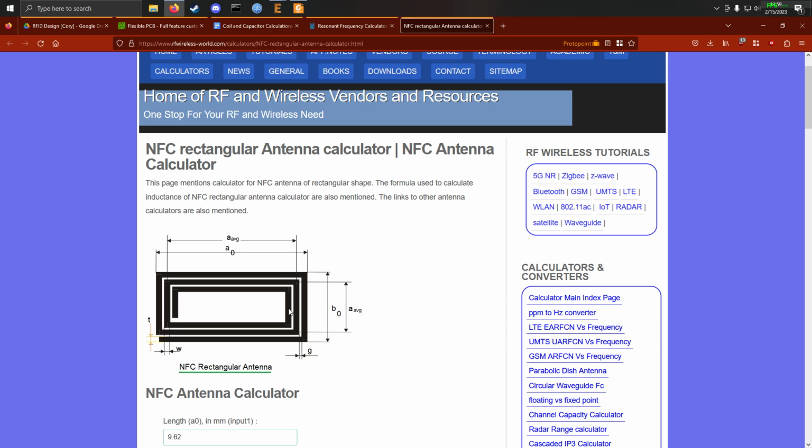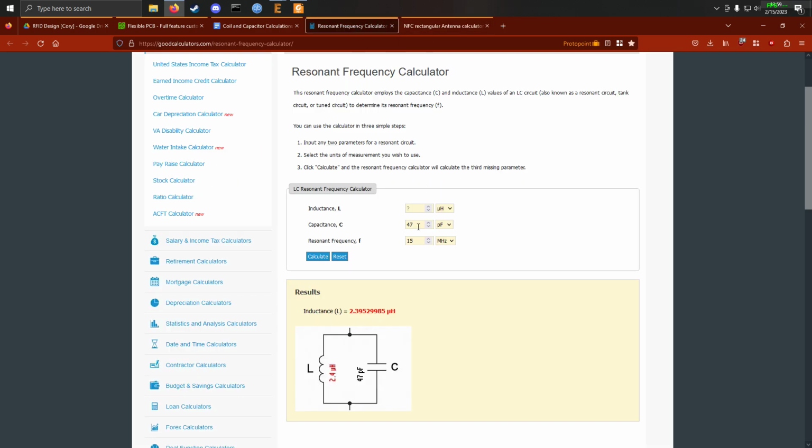So as you travel through this wire, which is a resistor, more and more of the voltage, relative to this point, over here is like 20% of the voltage. Over here is like 60% of the voltage as you travel through. So because of that, there's a little bit of capacitance called parasitic capacitance between the windings. So this value is not going to be exactly accurate.